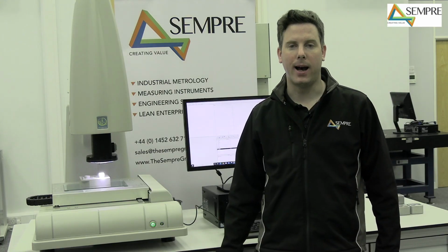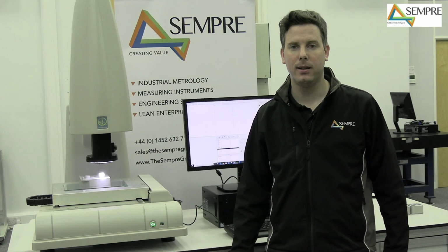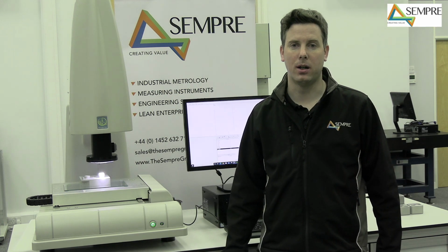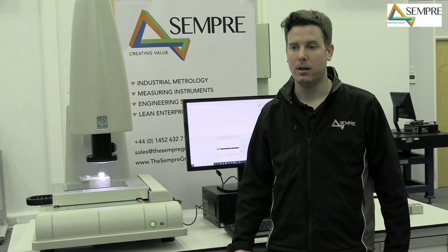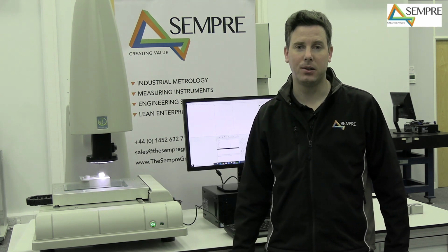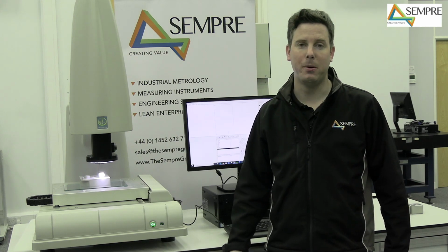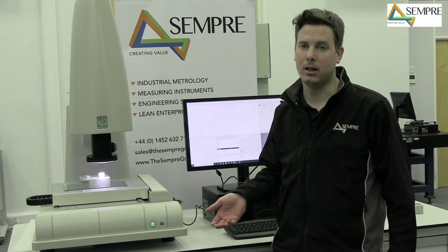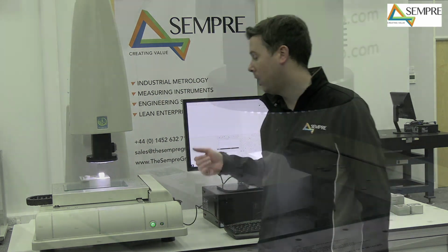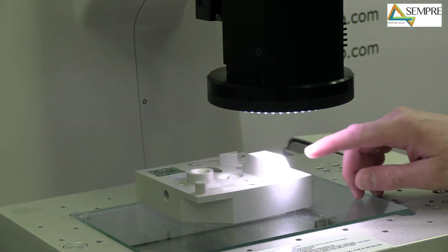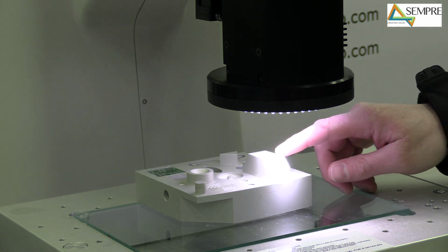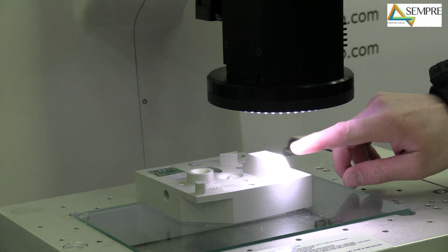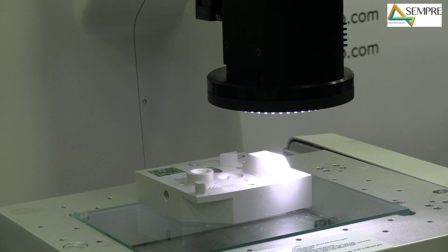Now we're going to move on and look at changing a working plane, and this is a very useful feature. It allows us to check angles down chamfers and things like that we wouldn't normally be able to measure when we're just looking down on the part. So for this example, I've got a part on a machine, and we're just going to be looking at measuring a line on this top face and then a line down this angled face here. That's all we're going to do today.